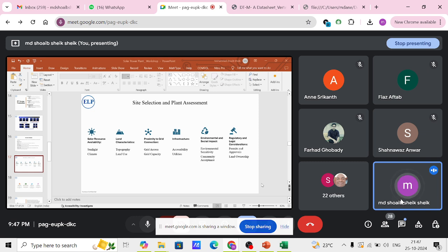We can't overload the transformer more than 75 to 80%. If I have 100 homes, and the transformer capacity is, just as an example, 100 kilowatt, we can't give more than 80 kilowatt on that. We need to check that as well with the government. Can we add my solar system to your transformer, whether it is suitable. If they say it's suitable, yes, you can go ahead.